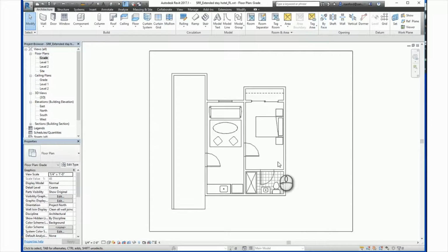There are basically two methods for creating stairs in Revit. You either use the stair by component method or the stair by sketch method. You can also combine both methods to achieve specific requirements. The component stair is parametric. The creation process is straightforward, but is generally seen as less flexible than the stair by sketch method.